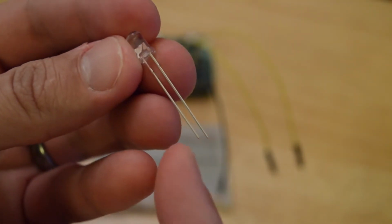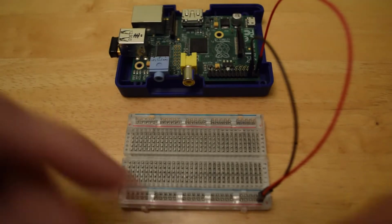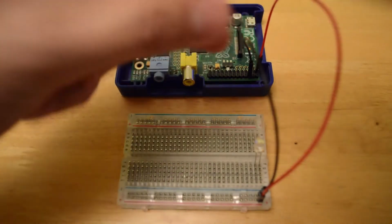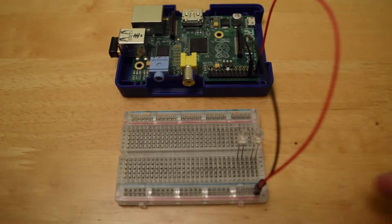So the LEDs have a longer pin on one side, which is the positive leg, and the short side is the negative leg, and you have to make sure that these are put in the right way. So in the diagram we have the positive leg going to the positive line and the negative leg going to the negative rail, and so for the way we've laid out this breadboard, the longer leg, the positive leg, goes on the right hand side. So just make sure you get that right when you wire it up, otherwise they won't work. Okay, so those two LEDs are plugged in.